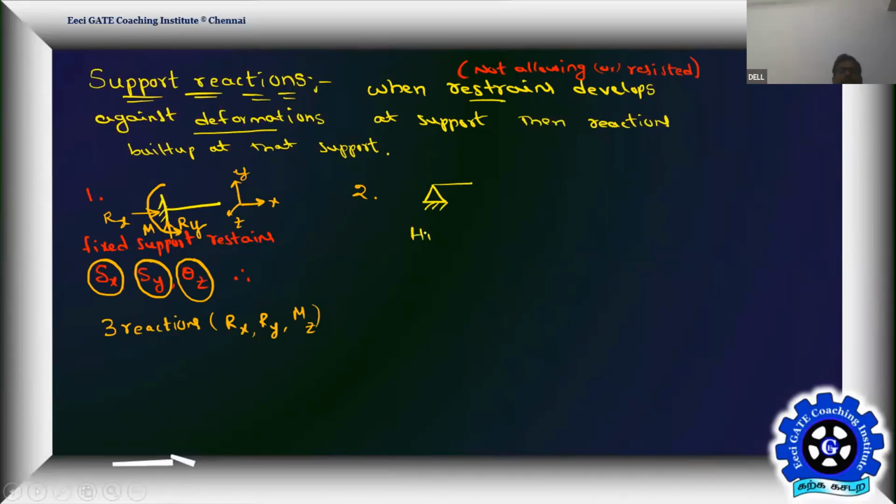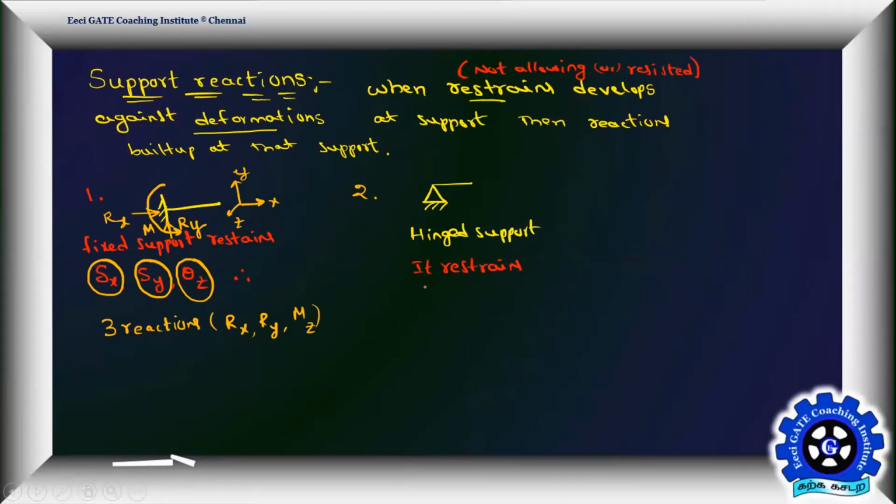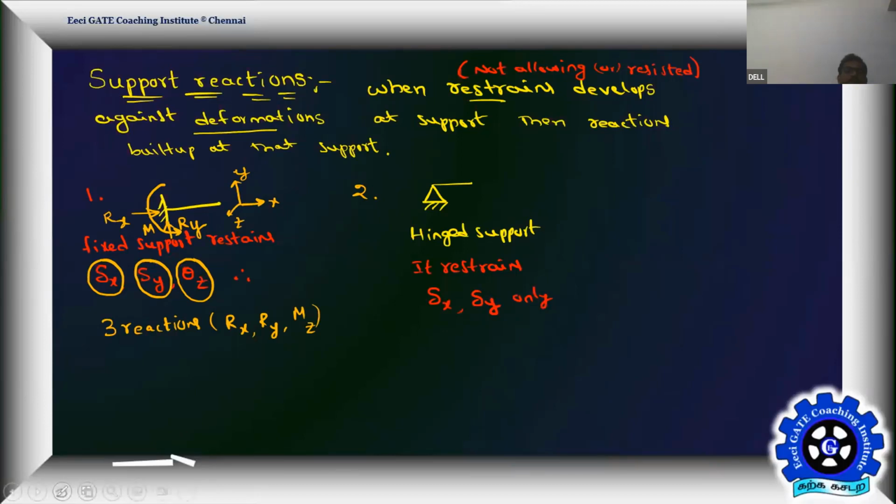This is what we call hinged support. Now, what does a hinged support restrain? Can you please tell me? Hinged support, it restrains what moments, what directions? X and Y, sir. It restrains displacement in X direction and displacement in Y direction only. But there is no rotational effect.